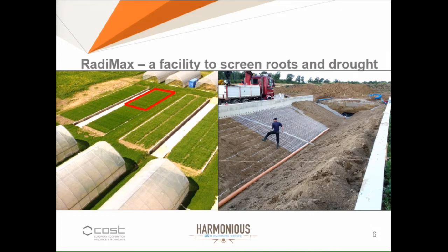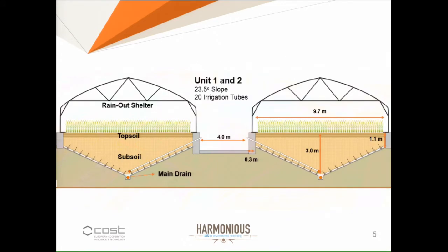So we removed it. And as part of that, we designed an underwater subsoil irrigation system. Down here, there's a gravel layer, so we prevent all capillary forces of water from coming up. Then we installed an irrigation system based on drip irrigation and water absorbing materials. And we can make a gradient of water down here, so we can actually water, creating a gradient following this slope.